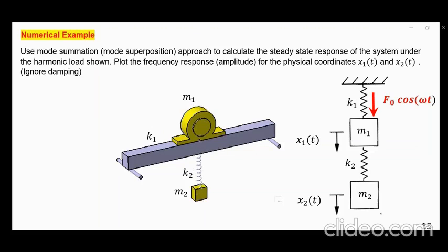This mass is usually much smaller, so that instead of the motor oscillating violently because the speed of the fan is close to the natural frequency of the beam, this mass absorbs that energy and starts vibrating violently as opposed to the actual structure.